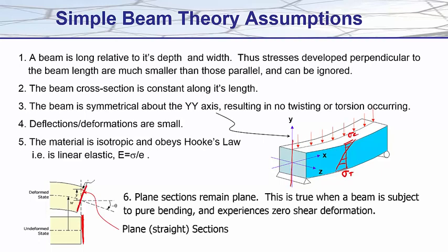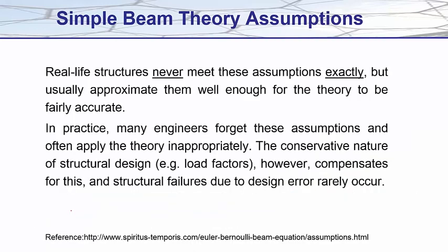Now, real-life structures never meet these assumptions exactly, but usually approximate them well enough for the theory to be fairly accurate. In practice, many engineers forget these assumptions and often apply the theory inappropriately. However, the conservative nature of structural design, having load factors of 1.2 on dead load and 1.5 on live load, often compensates for this, and thus structural failures due to design very rarely occur.